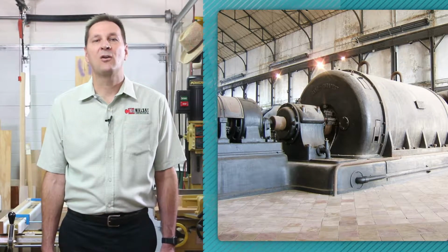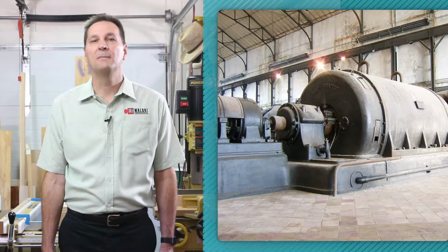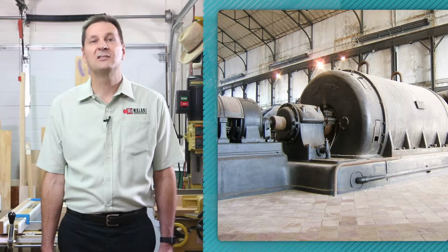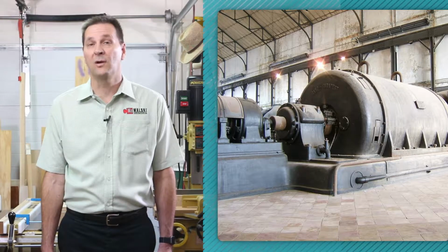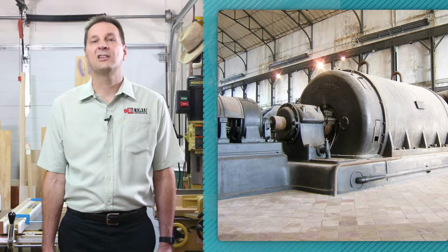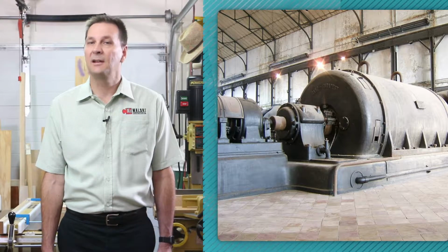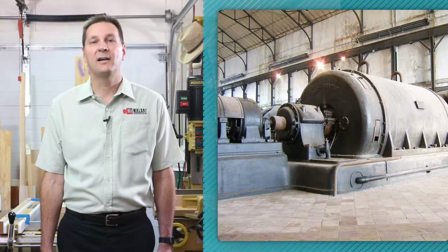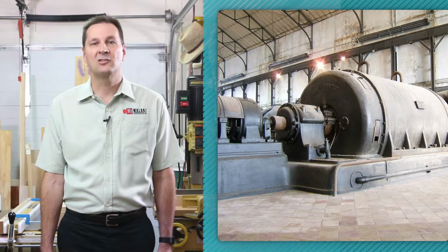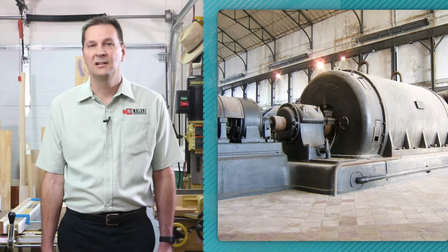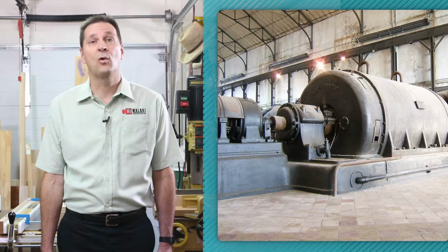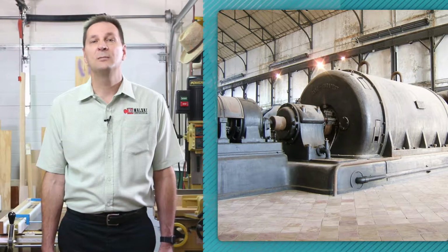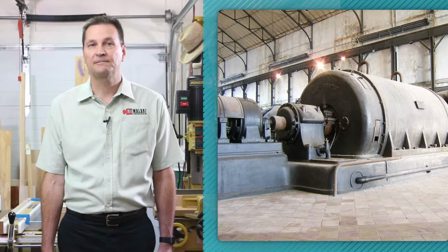Let's say that you have a power plant that can produce 1,000,000 watts of power. One way to transmit that power would be to send 1,000,000 amps at 1 volt. Another way to transmit it would be to send 1 amp at 1,000,000 volts. Sending 1 amp requires only a thin wire, and not much of the power is lost to heat during transmission. Sending 1,000,000 amps would require a huge wire and generate a lot of heat, which would be lost during transmission.